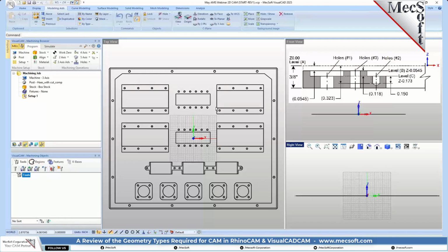You can use a 3D model to do 2-axis operations. Any curve, any edge of a surface, or any basically edges and curves in a 3D model, when you pick those, it'll project those down to your XY plane, or where you're actually going to be drilling or cutting in what level, okay? So for 3-axis, you have to have a minimum of a surface, a poly surface, or a NURB surface, or a mesh, okay? So you can machine a mesh or surface. For boundaries, to contain your drawing, you can use curves, okay?